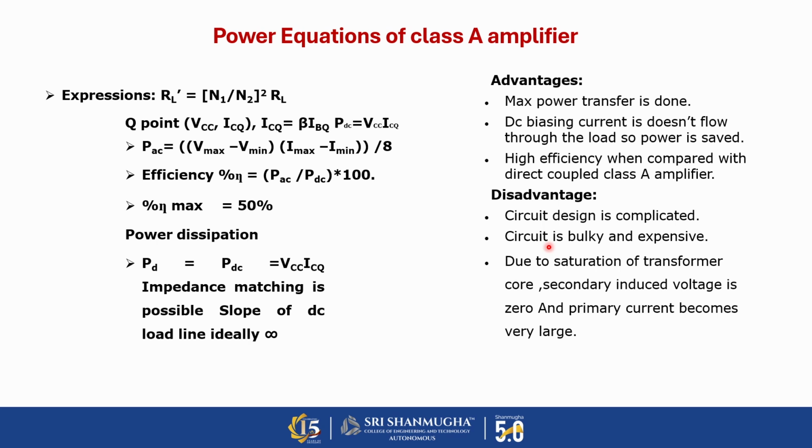The disadvantages are that low frequency signals are comparatively less amplified, the frequency response is slightly poor, and the transformers are bulky and costly due to the presence of the transformer in the amplifier circuit.